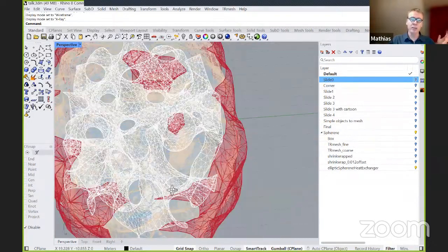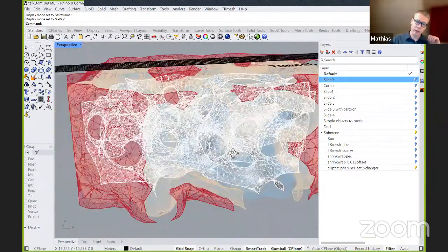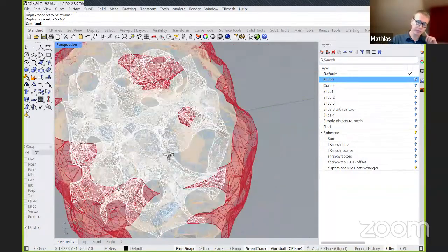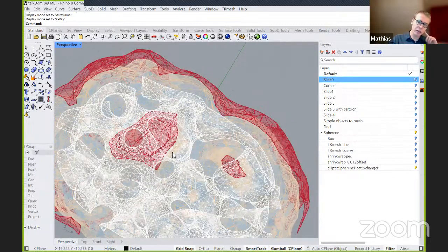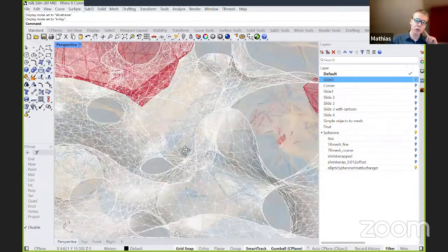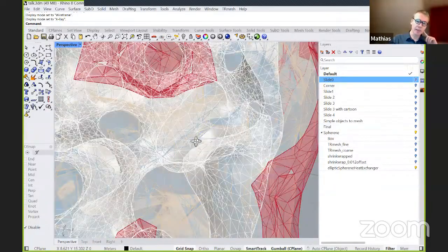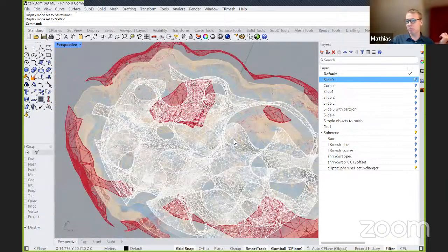So this minimal surface here in the middle is just a minimal surface I got from the great guys at Spherene, and it's the middle wall of a heat exchanger. So one side of this mesh is a cold side and the other side is the hot side. And now imagine we want to give our heat exchanger a thickness, and that's where Shrinkwrap comes in.